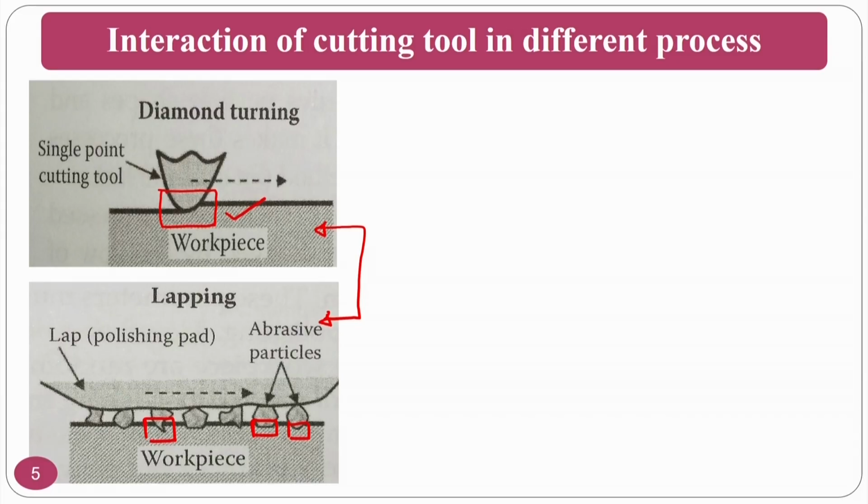For that purpose, what will be the solution? In this particular thing, we do not want feed marks, even though we are getting a very good surface roughness and figure in terms of diamond turning as well as lapping. But the problem in these conditions is that you are going to get the physical feed marks, which are nothing but the scratches or lines on the lenses.